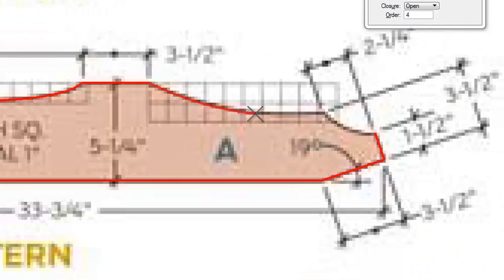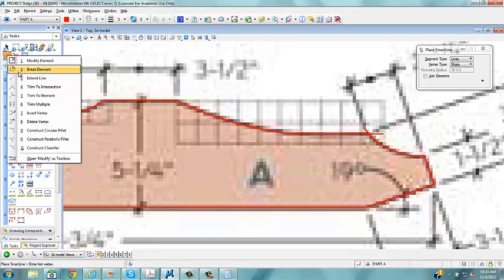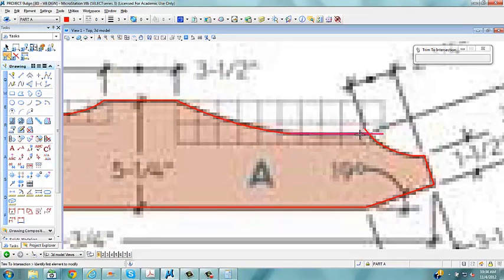Same thing over here, we're just going to let it snap to this end point. Still staying out of the AccuDraw, we're going to go right down onto the bottom. It looks like a straight line there, so we'll come over here. And again, this is just, imagine taking your table saw and just cutting that. I'm just going to extend it up a little bit further here. Go back to our Smart Line tool, just extend this across, and then we'll trim that out using this tool.